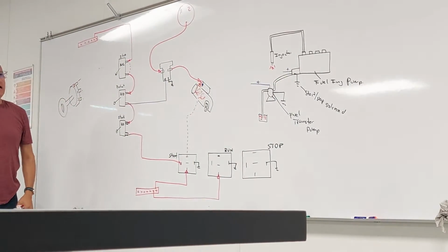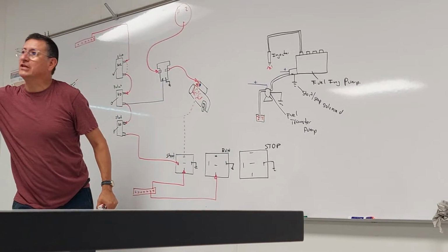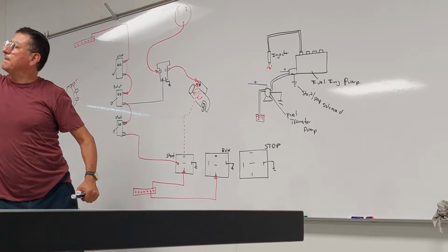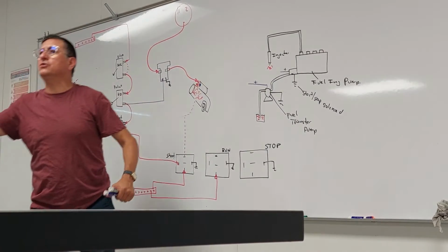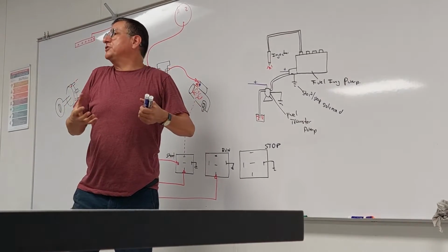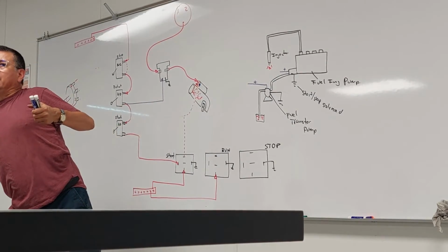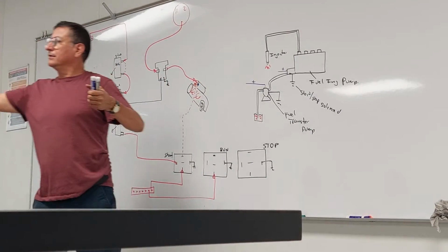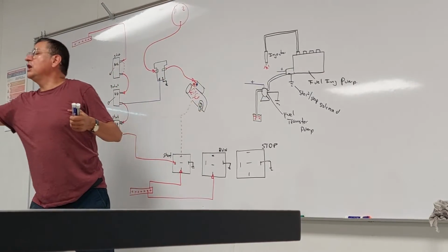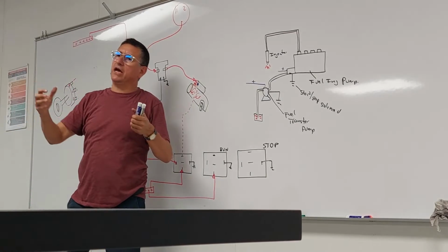The transfer pump is the pump that you hear in your car when you select ignition. This is the pump that brings fuel from the fuel tank into the fuel injection pump on the engine. This is considered a low pressure pump, only to bring the fuel from the tank into the engine.